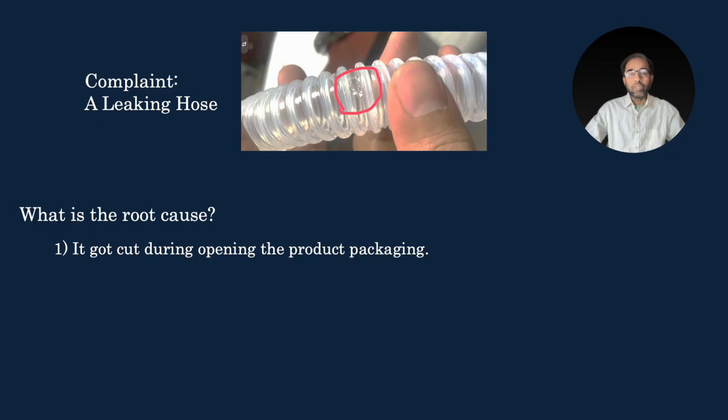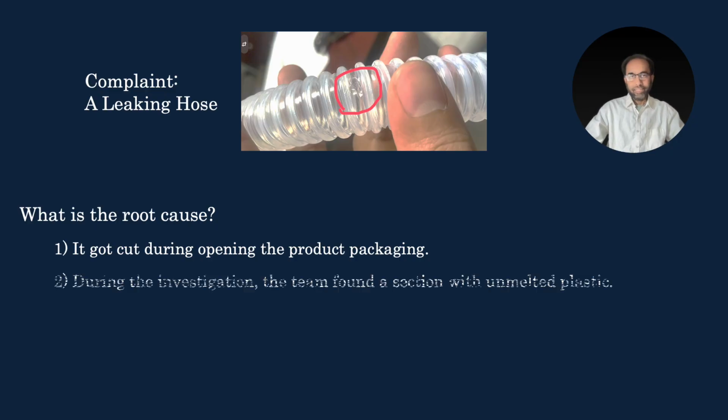And recently I'm hearing that after investigation by one of the facilities involved in this situation, the team found a cold slag or unmelted plastic. Now I hear that that is the root cause. So which one do you think is the root cause? Are both of them the root causes, or which one? We'll come back to it later. You just make your choice and we'll come back to it later.